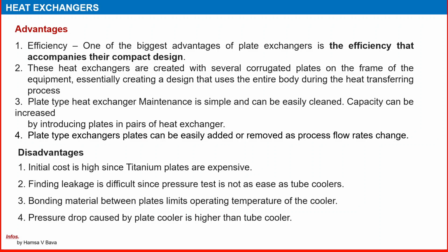Bonding material between plates limits the operating temperature of the cooler. Pressure drop caused by a plate cooler is higher than the tube cooler. So advantages and disadvantages are there. So we will get a clear idea of what the advantages and disadvantages of plate type heat exchanger are. If you get a chance to visit your field, if you have a plate type heat exchanger in your field, just visit and see the inlet, outlet and constructional details and how the plate and frame is arranged. So you will get very good clarity on the subject.